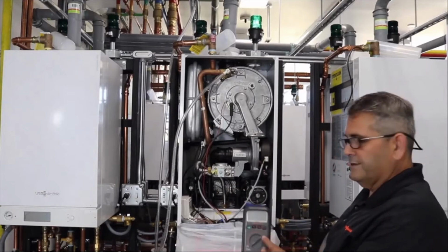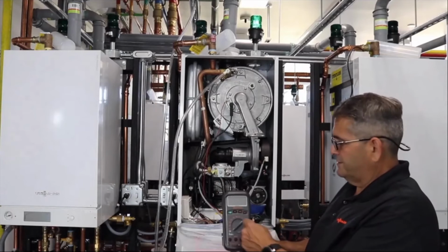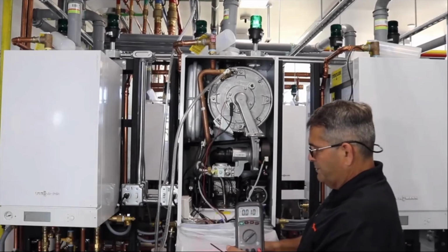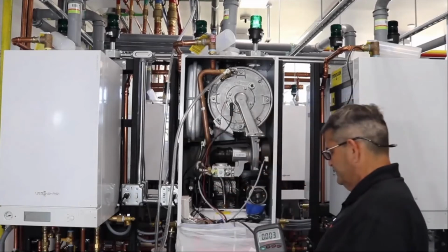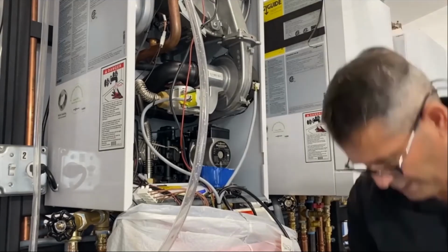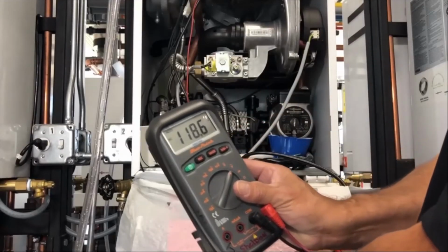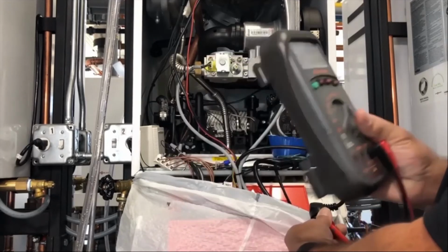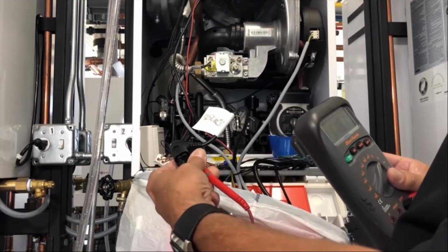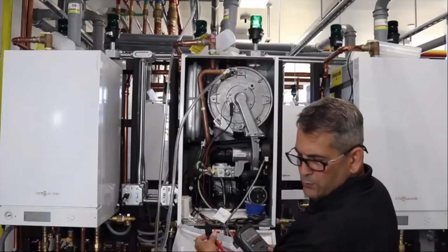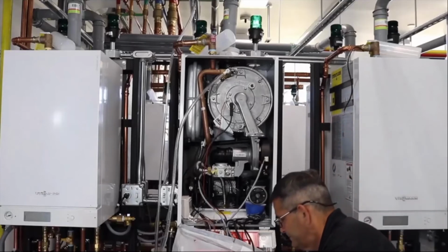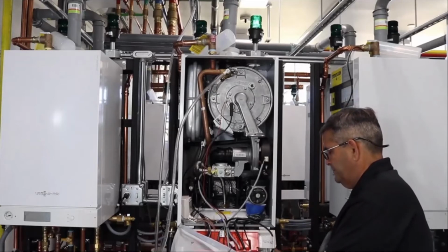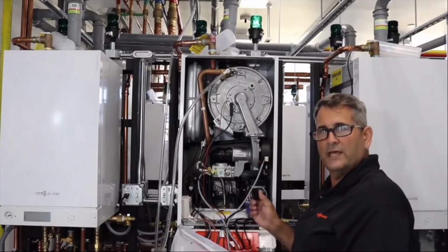We're going to stick it on AC current. Once we do that, we're going to now come up here and check for 120 volts, but we do have to turn the power on. And we're going to check for our power here. Once we do that, we now have the 120 volts or 118 volts in this case here, and we're going to the 2 outer parts of our test part. So we know we do have power here at our pump. So we can shut the power down once again. So we know we do have the 120 volts at our plug.